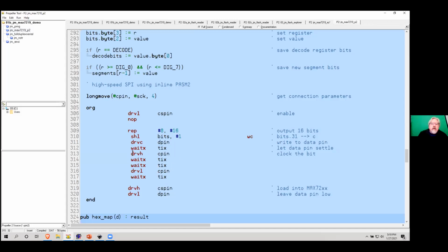Thank you. And now we take the clock pin high. Now we have 2/4, so that's doing our high pulse on our clock line. We drive the clock low, and then we're going to wait another 1/4 SPI clock cycle and do the whole thing over again. It's a few more lines of code, but now we have more precise timing.